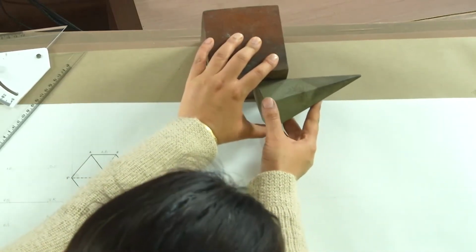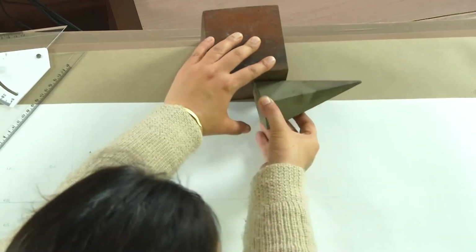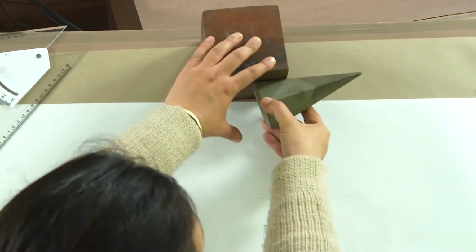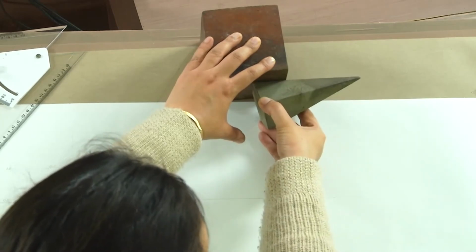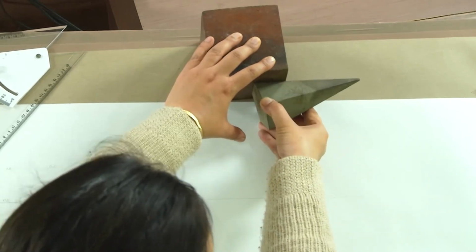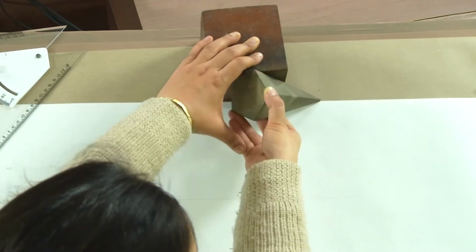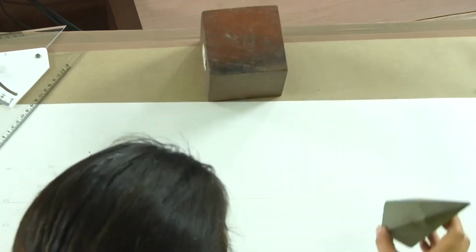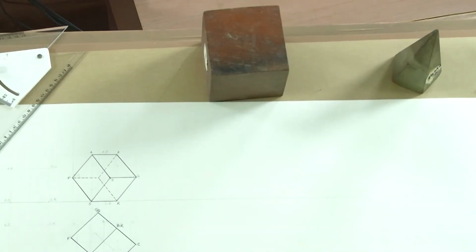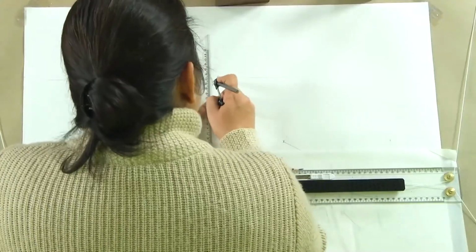So, that is one inclination and the axis is still parallel to HP. So, we will still be seeing the true shape. And now, if it further makes an angle with HP, we will be inclining it further. That is how the movement of it would be. So, let us assume a pentagonal pyramid with a base of 3 centimeter side, and let us quickly draw this pyramid first.